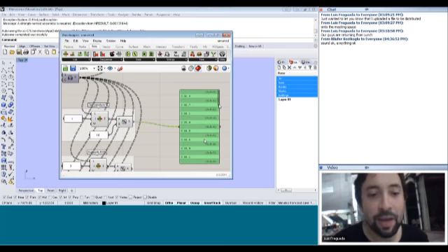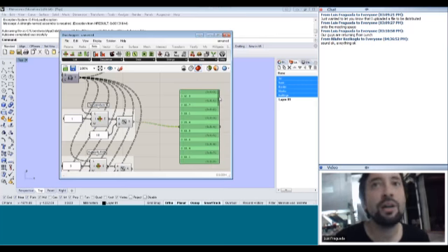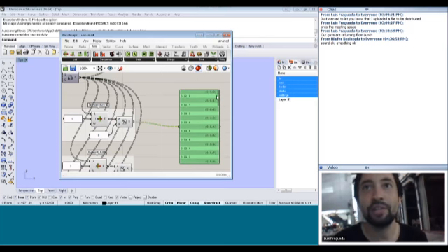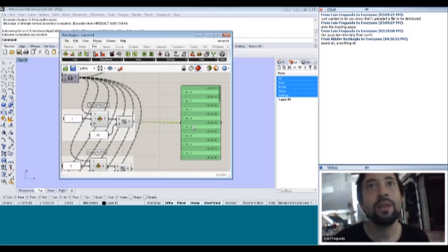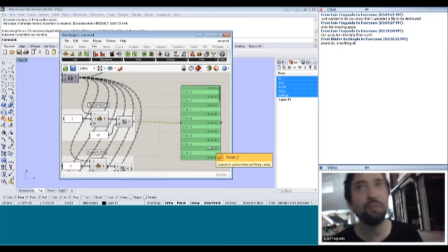From now on, it would be much easier to work with my temperature values if they were actually just in one list, not in a bunch of different lists that don't really relate to each other. So one thing that you do sometimes when we're dealing with data trees is you want to remove all of this extra structure, all of this extra separation and indexing, and just put everything in a list like we knew before. So 0, 1, 2, 3, 4, 5. Something that's a little bit easier to play with.